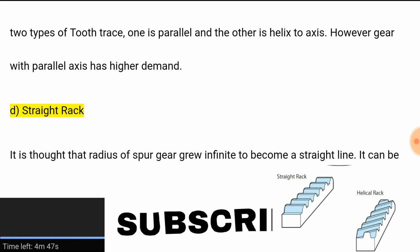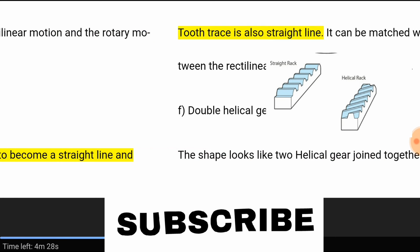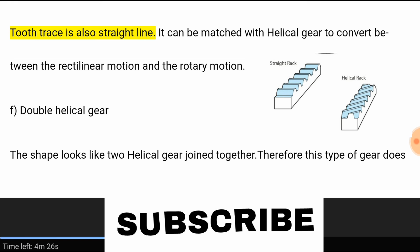D. Straight rack. It is thought that the radius of a spur gear grew infinite to become a straight line. It can be matched with a spur gear to convert between rectilinear motion and rotary motion. E. Helical rack. It is thought that the radius of a helical gear grew infinite to become a straight line and the tooth trace is also a straight line. It can be matched with a helical gear to convert between rectilinear motion and rotary motion.